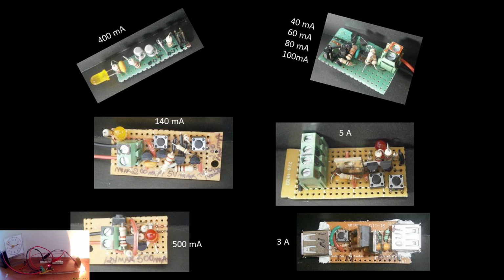As you can see by the picture, I have got a collection of circuit breakers, from part 1 to part 5 videos, each one with a different current limit. I use them to protect against high current, or short circuits, when doing breadboard testing for new projects.